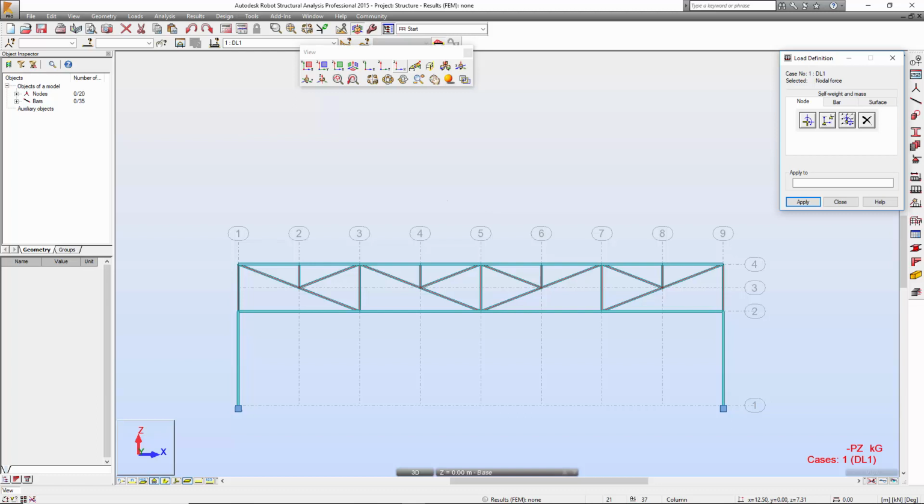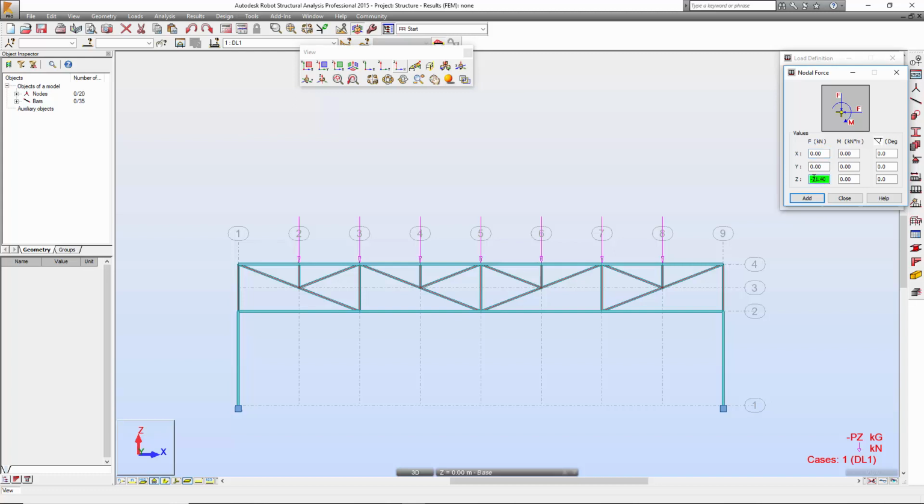You will see that your cursor has changed to this applying mode for applying the node force to the joint. So let's click on this one. So you got the first point force on, and then click on second, third, fourth, and then all of these have the proper loading on. And then after that, you need to change the loading to 75.7, because it's half of it.